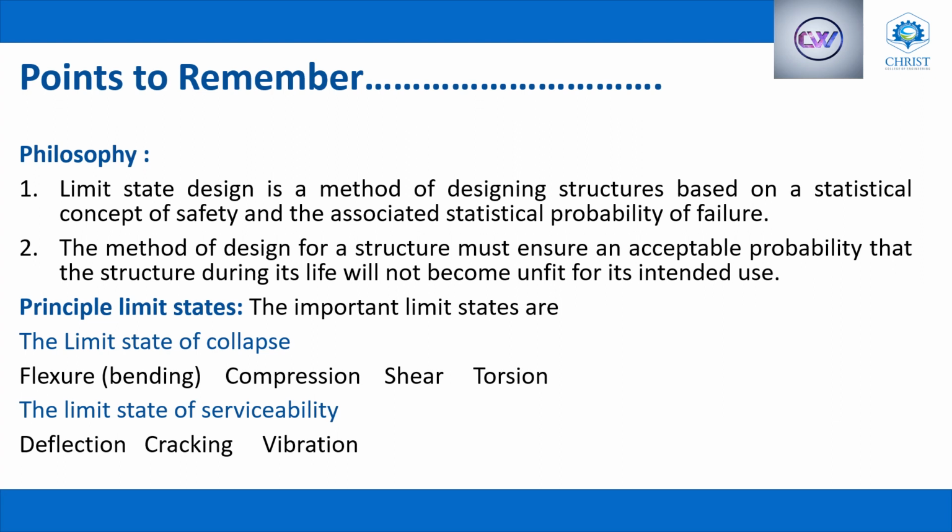The method of design for a structure must ensure an acceptable probability that the structure during its life will not become unfit for its intended use. Then the principal limit states are, first, the limit state of collapse and, second, the limit state of serviceability. The limit state of collapse means limit state in flexure, compression, shear and torsion. Limit state of serviceability means limit state of deflection, cracking and vibration.